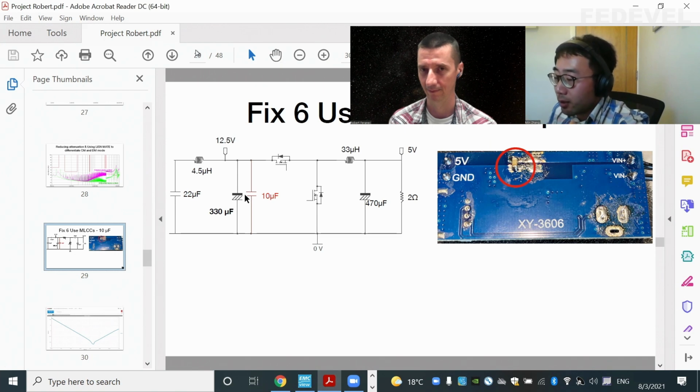And it's the fact that the load asks for energy from everywhere that creates the common mode noise. So if I can deliver the energy immediately from a differential point of view, I will still be able to suppress the common mode noise.